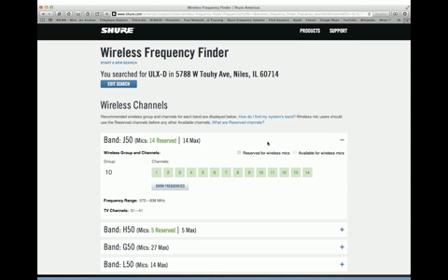Right. And getting back to the frequency band issue again here too. So all of these 4 frequency bands that are available for ULXD, these numbers you see here are shown in isolation. That means you can use up to 14 J50s or 5 H50s or 27 G50s or 14 L50s, but you can't use 14 J50s plus 5 H50s plus 27 G50s plus 14 L50s. That's a good distinction.